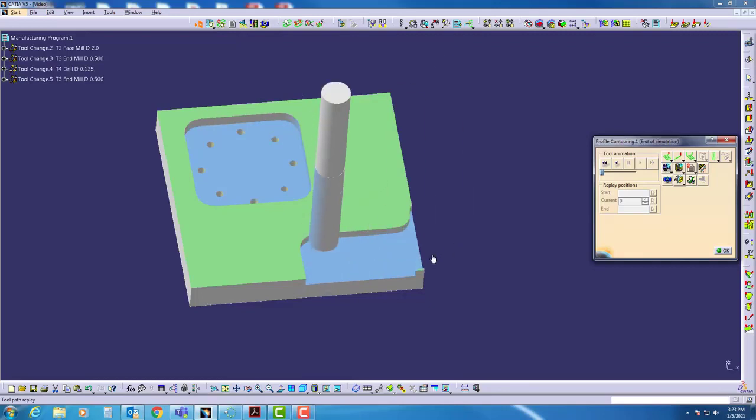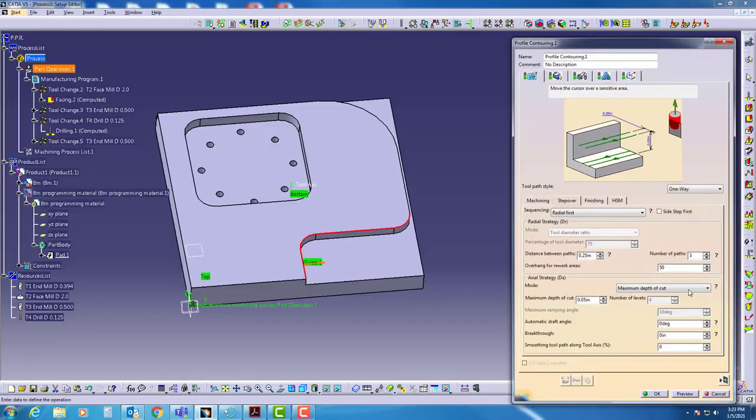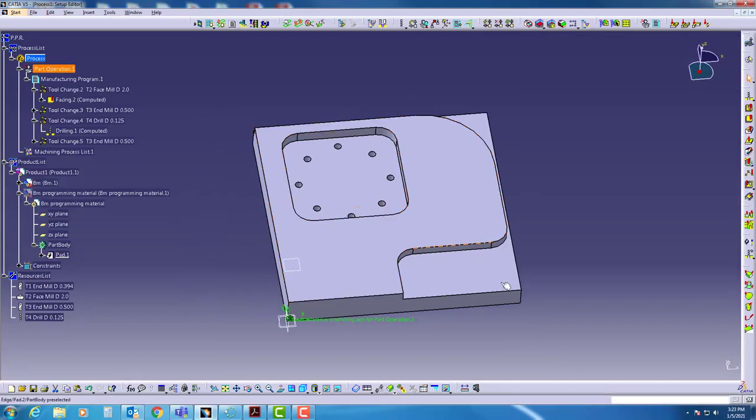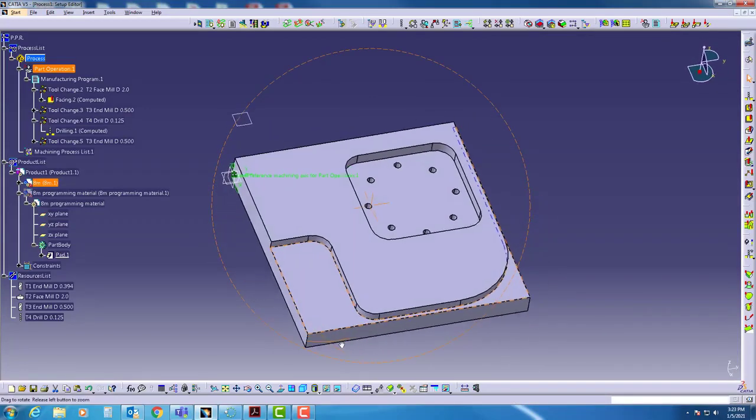So 2 things we'll look at is, 1, I've got a little bit more here, and after I fix that, we'll go on to finishing the rest of the part. So on my step over, we'll just change that to 300 thousandths, hit enter, and we know that will work. So we'll hit OK. So now we've got to do the rest of my profile.